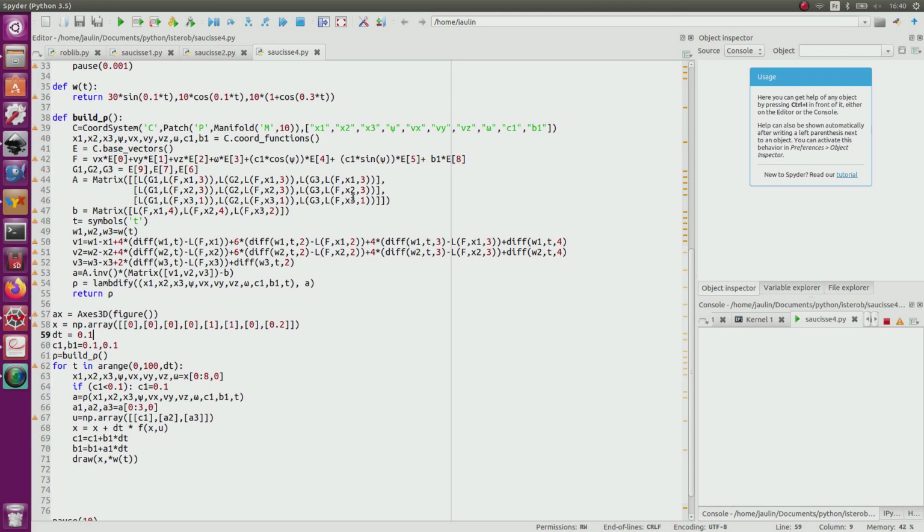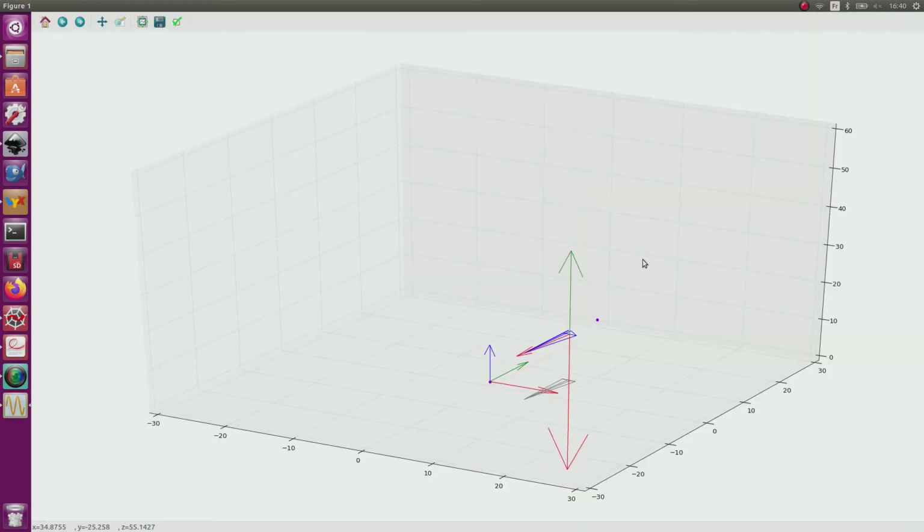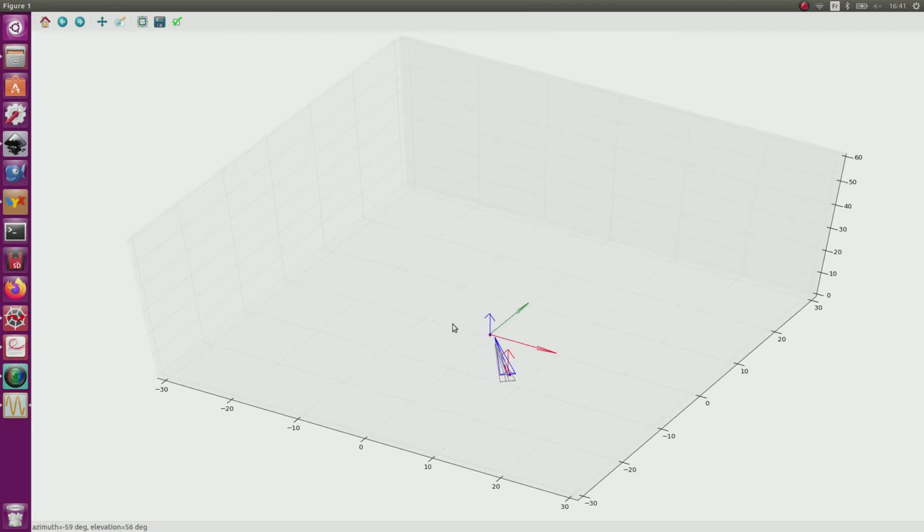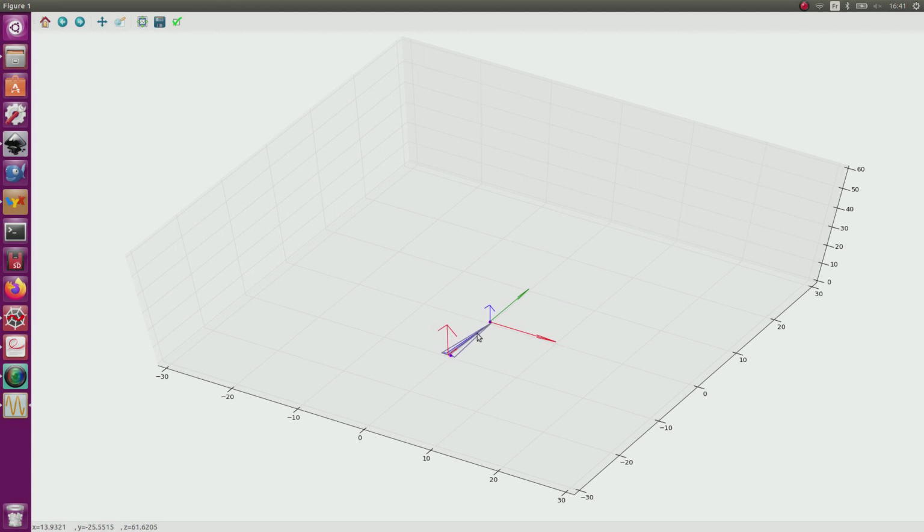I run the program. I can see that the AUV reaches the target point. In red, I represent the longitudinal and the vertical propulsion. And we can see that it follows exactly the reference point. The orientation we have for the robot is mainly due to the fact that the propulsion is only allowed with respect to the axis of the robot. This is why it has to orient toward the origin so that it will be able to turn around it following the Lissajous curve.